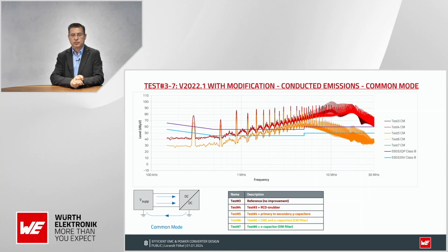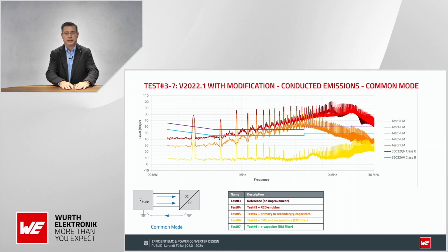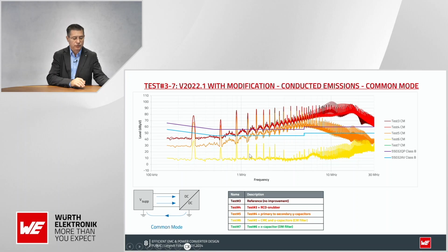In this case for common mode noise, we put the common mode choke with the Y caps activated. Then we saw, okay, the common mode choke, as expected, does this job, and we have a very nice rejection. We have nice filtering. Everything looks fine, but we still have one capacitor to activate. This is the X capacitor, and look what happened in the low frequency, even for the common mode noise.